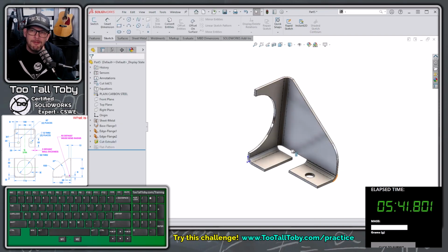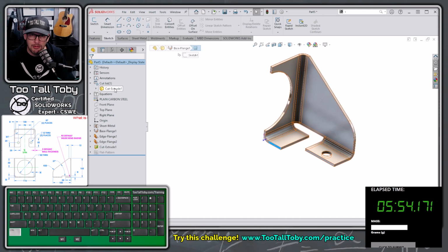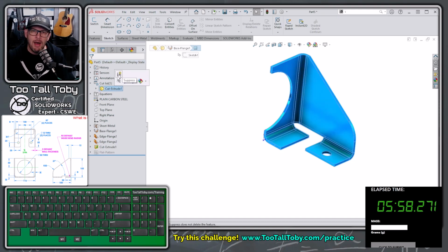And then one final shortcut here is whenever I'm mirroring geometry, I like to add the mirror command into the context menu when you select a face and then you hold control and you select a solid body. So I select this face here, I hold control, I select this solid body. Now I want the mirror command to show up automatically in this menu.